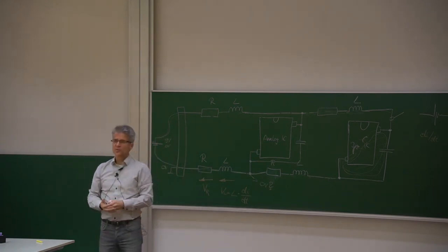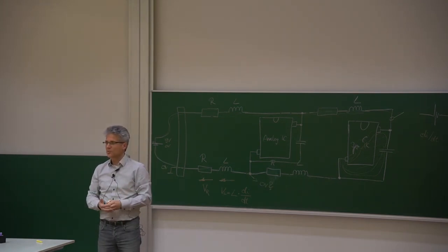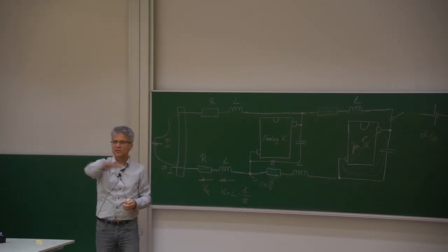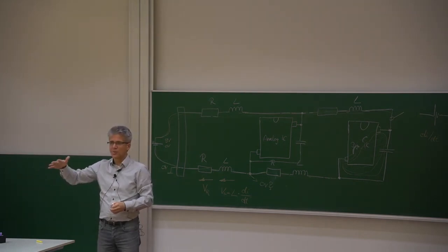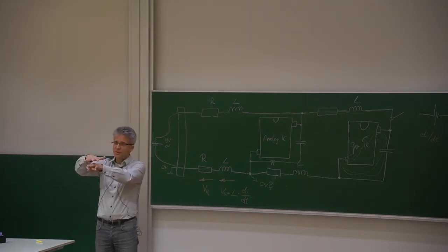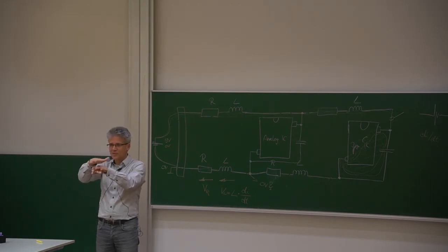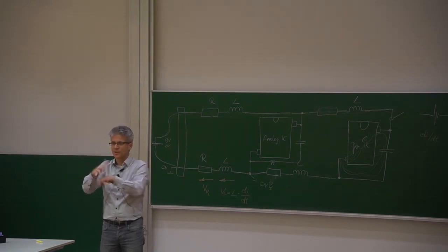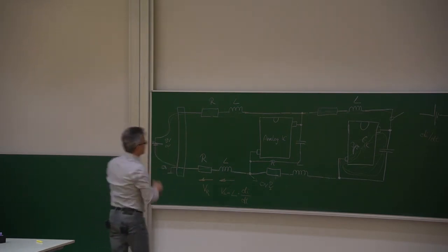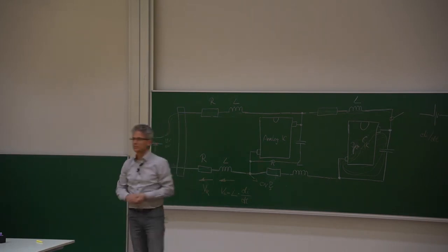Preferably use a multi-layer printed circuit board design, where one layer is acting as a signal return layer and the other one next to it, at a very close distance, is a very big layer acting as a VDD layer. This gives you an additional benefit because this is also a very good capacitor. And this is the best decoupling capacitor that comes for free. And then the loop area is the smallest that you can get. Okay, so shrinking everything and making the loop area small.